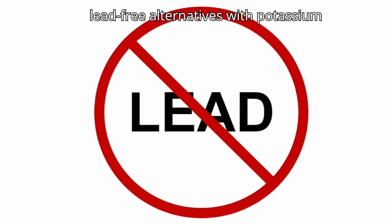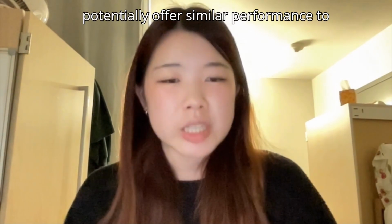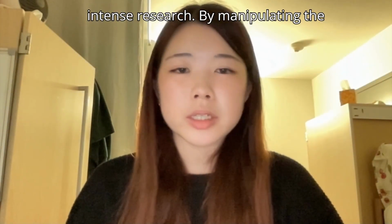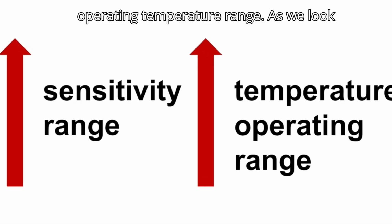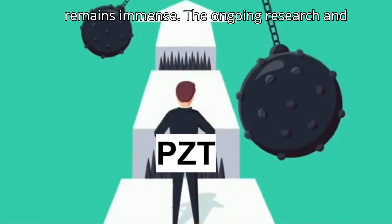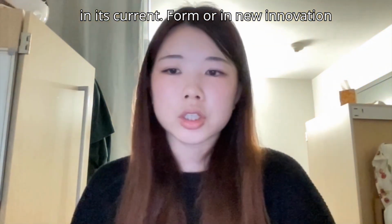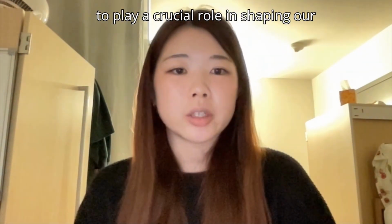Ongoing research is addressing PZT's limitations head-on. Scientists are developing lead-free alternatives, with potassium-sodium niobate-based materials showing particular promise. These could potentially offer similar performance to PZT without the environmental concerns. Nanostructured PZT is another area of intense research. By manipulating the material at the nanoscale, researchers aim to enhance its properties, potentially increasing its sensitivity or operating temperature range. As we look into the future, it's clear that while PZT faces challenges, its potential remains immense. The ongoing research and emerging applications promise to keep PZT at the forefront of piezoelectric materials for years to come. Whether in its current form or in new innovative variations, PZT will undoubtedly continue to play a crucial role in shaping our technological landscape.